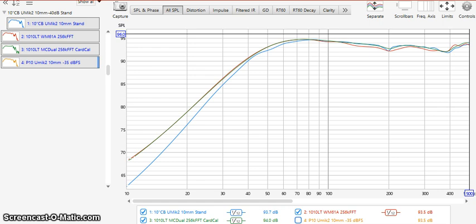Something was different. Now, of course, I played with REW settings in the meantime. Suddenly I noticed the Panasonic microphone sloped down a little too much too, and I thought, uh-oh, something's not right here, so I kept digging into it. I finally found what is at least the problem partially with the slope. If you're using REW for close mic measurements, whether with the driver or passive radiator, or I assume it will also be the same for a port, I've not tested that, there's a control within REW that has an impact on that, and that's where the primary problem was.